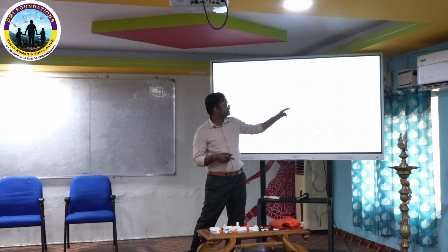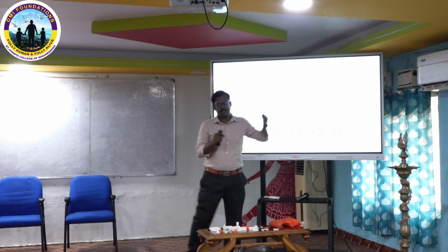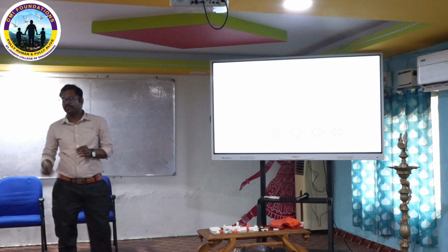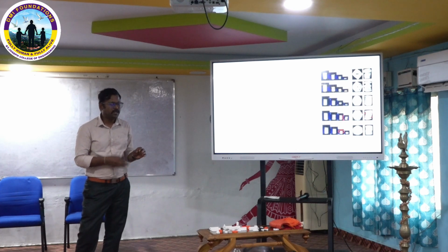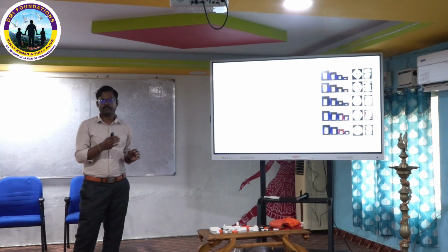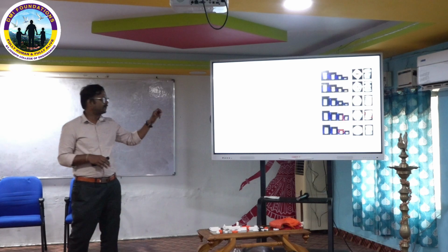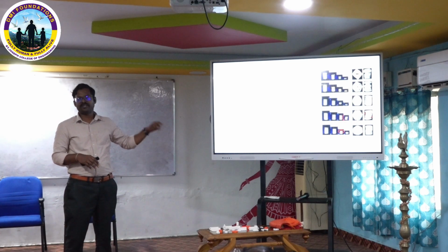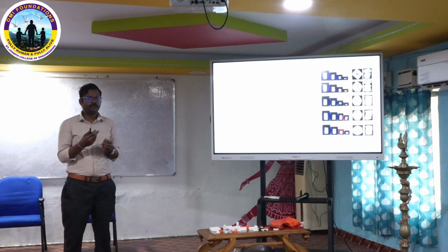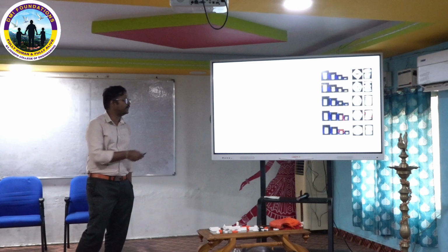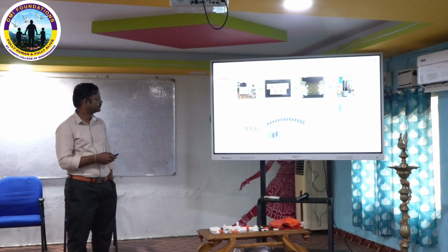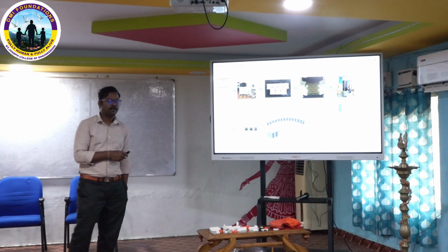But when I compress these two, the outer cube structures get stretched outside, so global buckling happened. During the compression, my sample came out in between and the compression test was stopped. So I finally conclude that these structures are not suitable for energy absorption application. Why? Because they show stretch-dominated behavior, so they will not absorb that much energy. So in this work I completed this one. These are the data.